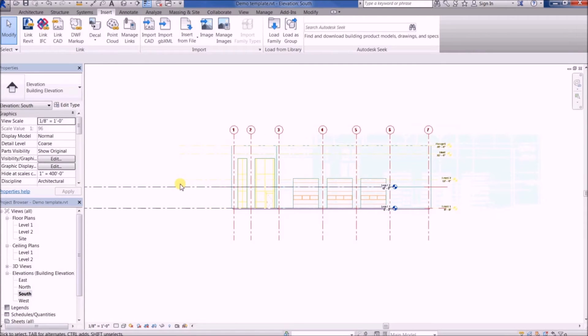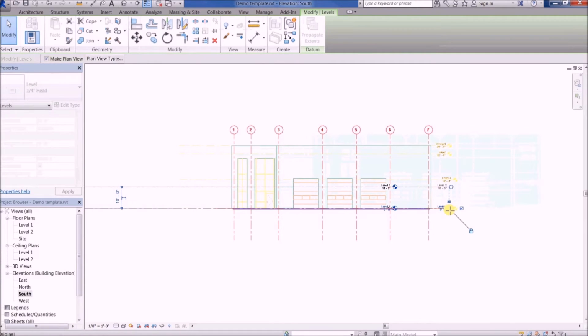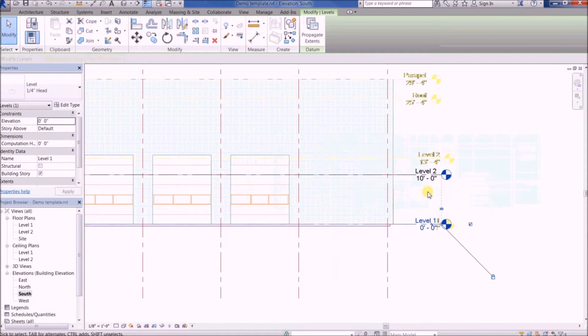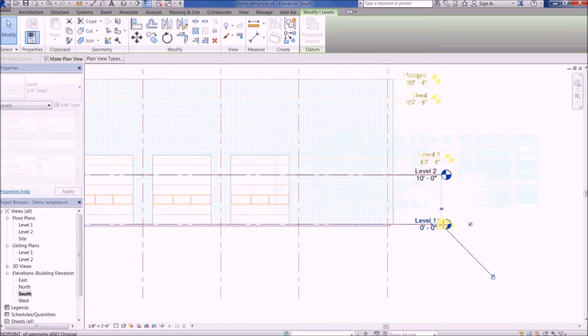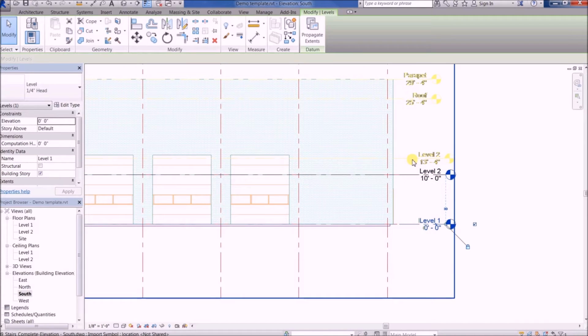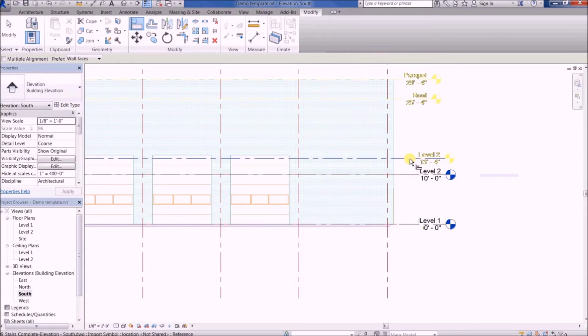We have these two levels in Revit. These levels you can adjust. I'm going to adjust the length of these so they kind of match the levels that came in with our AutoCAD file. So we have these levels that came in with AutoCAD. Kind of a little bit hard to see, but just eyeballing it, making it close. And I could take this Revit level and move it up to my AutoCAD level using an align command. So I'm aligning my Revit level to my AutoCAD level.